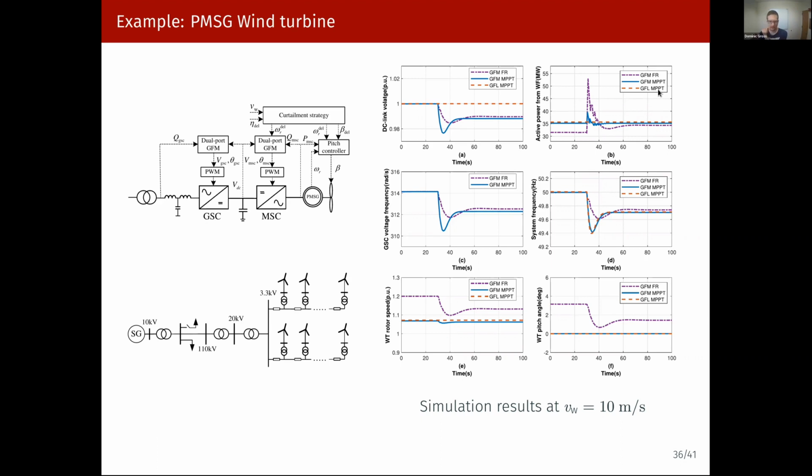And then if you curtail the operating point of the wind turbine and operate at a higher rotor speed, you're reducing the power production at the original operating point, but after the load step, you get this massive boost of energy released from the rotating mass by decelerating it. And then you also have a primary frequency response, so that after the contingency you get more power injection.